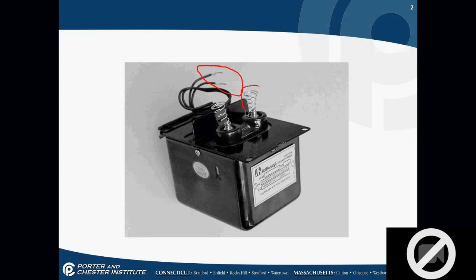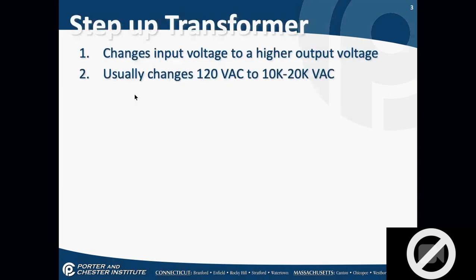I have two springs here. When this folds over and seals up onto the burner, these two springs are touching my electrodes. They're touching the long metal piece that comes out of the back of the electrode, and they have to make firm contact. Over time, these springs will wear out, as most springs do. When they don't make good contact anymore, you have to replace the springs. Your transformer will burn out before that anyways.